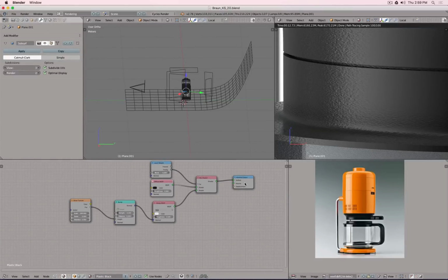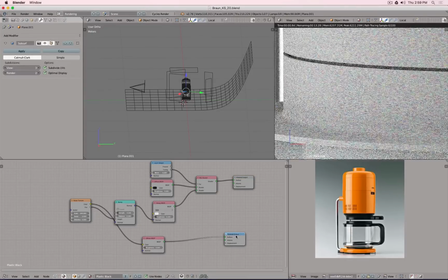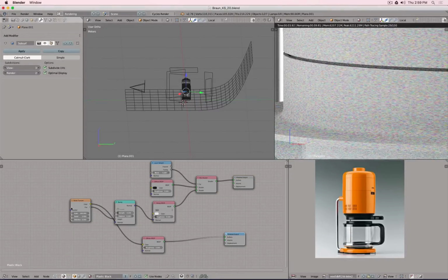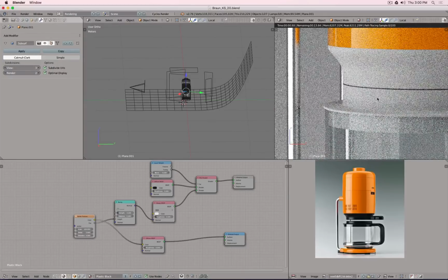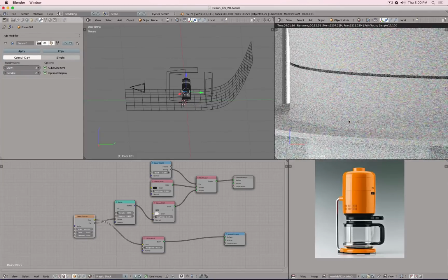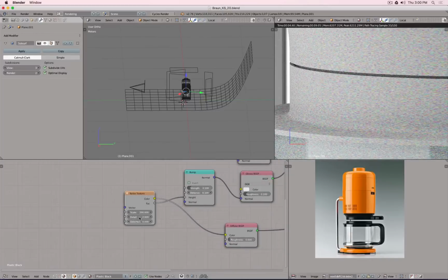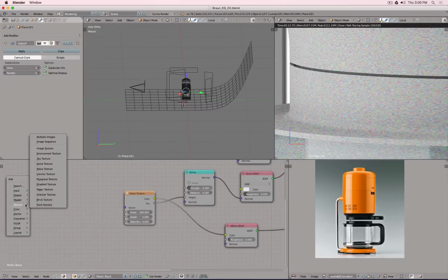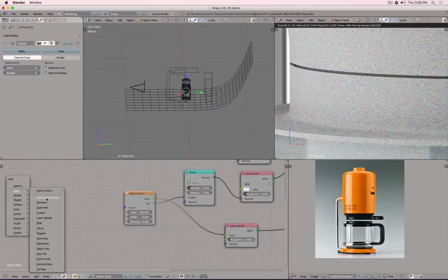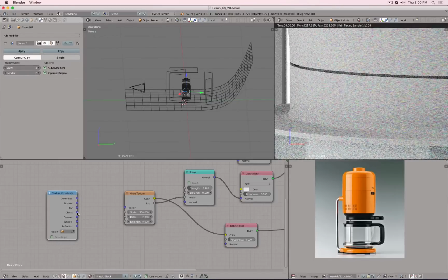So what I will do is this. Shift D, make myself a copy there, and then I feed this one to there. Click on this output because I actually would like to see how this noise texture just looks on a plain material. And there you can see that this is stretched. There's nothing here that really helps me to de-stretch it, and that's simply the basic mapping this function uses, and it doesn't really work with my object, so I have to override it. So we go back, input, texture coordinate, and say object. Object properly should work there.